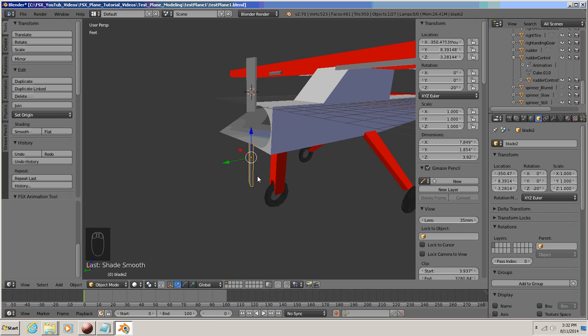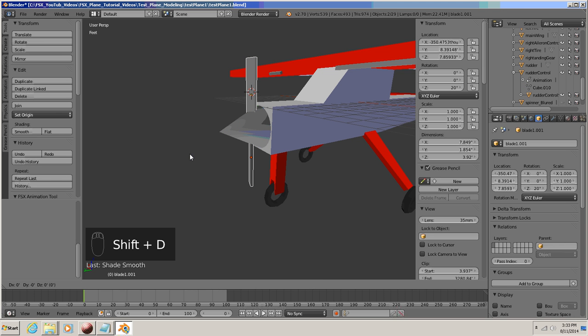Now with blade 2 still selected, let me think. Let's make duplicate copies of them. So let's click both. With blade 2 still selected, hit the shift key and select blade 1. Do a Shift D and then hit the enter key.